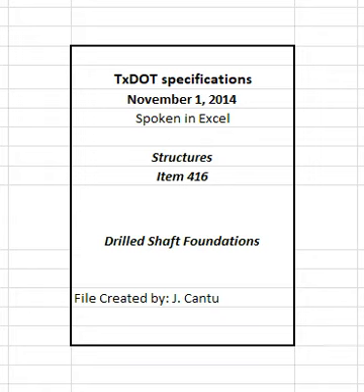For dry shafts over 24 inches diameter, concrete can be allowed to free fall an unlimited distance if it does not strike the reinforcing cage or sides of the hole during placement. Provide a hopper with a minimum 3 feet long drop tube at the top of the shaft to direct concrete vertically down the center of the shaft when free fall is used. Do not use a shovel or other means to simply deflect the concrete discharge from the truck.